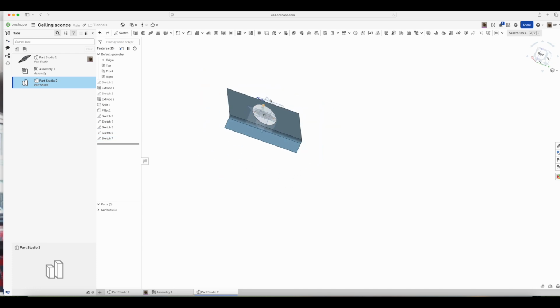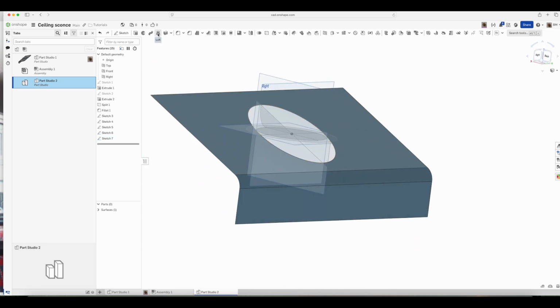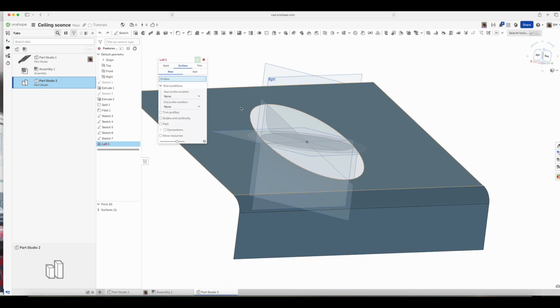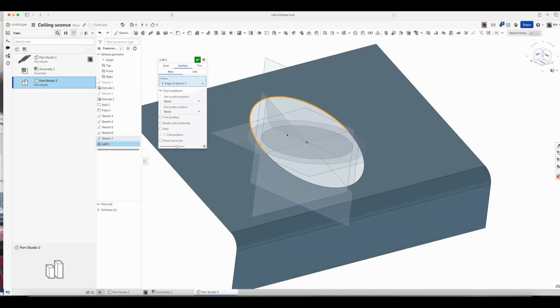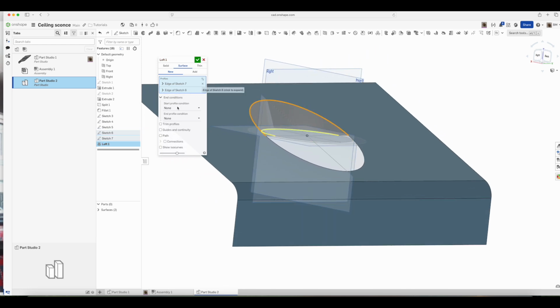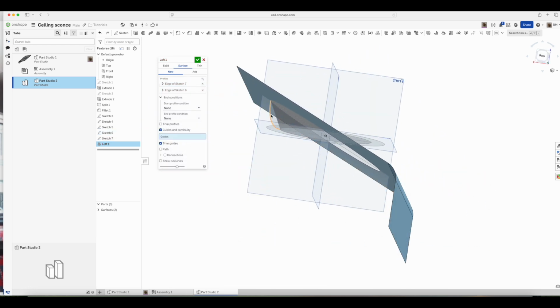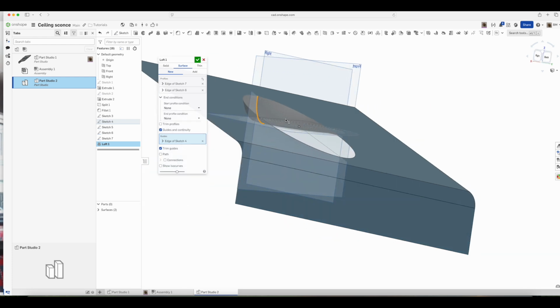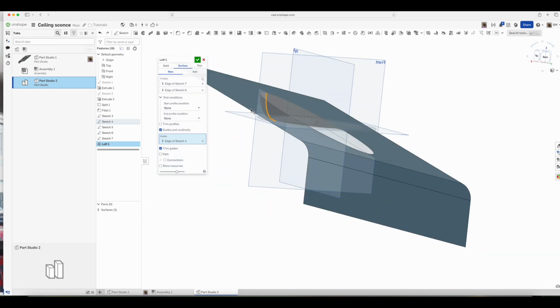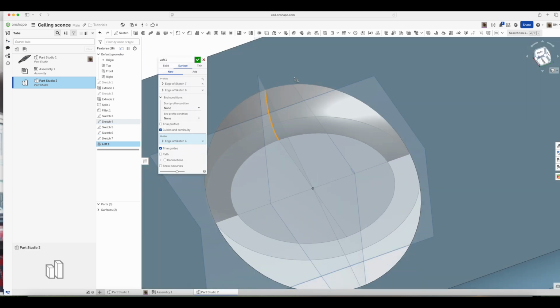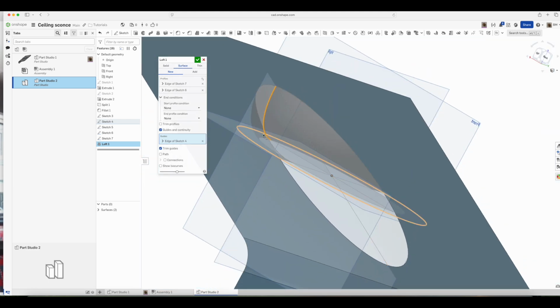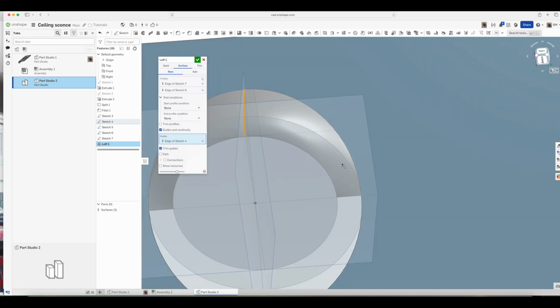Okay, now we're ready to generate the loft. And all the loft is going to be is a loft that's created from here down to here with this curve we made here as a guide. You can see there that fills out nicely. And what the guide is doing there is it's saying, okay, any point in the loft near that guide curve, it needs to follow that. And Onshape is blending it from end to end there.